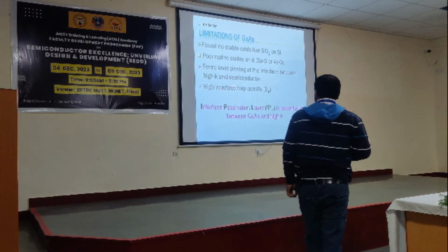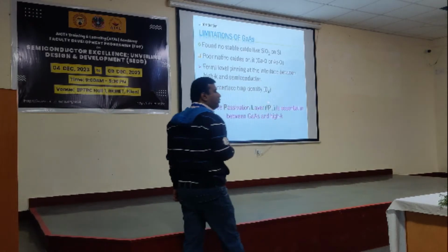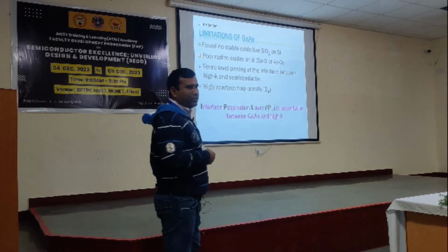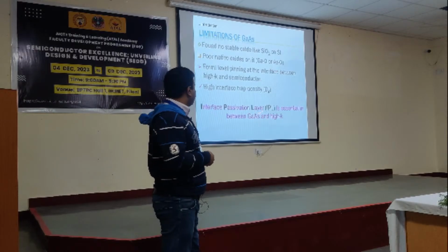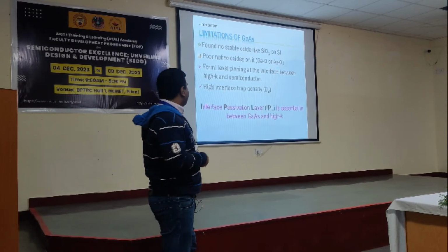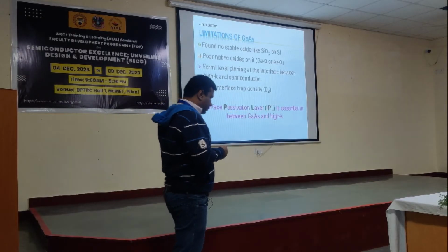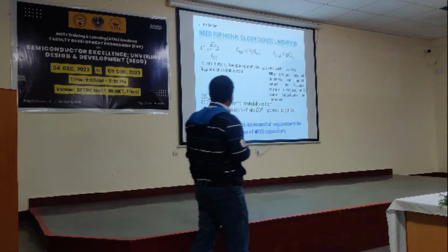That's why what we need to do prior to the deposition of high-K dielectric or any kind of material, before processing or your device fabrication, you have to passivate your gallium arsenide substrate by suitable material. That is called your interface passivation layer. So what is there here? In the process, in the succeeding slide, I will tell you.